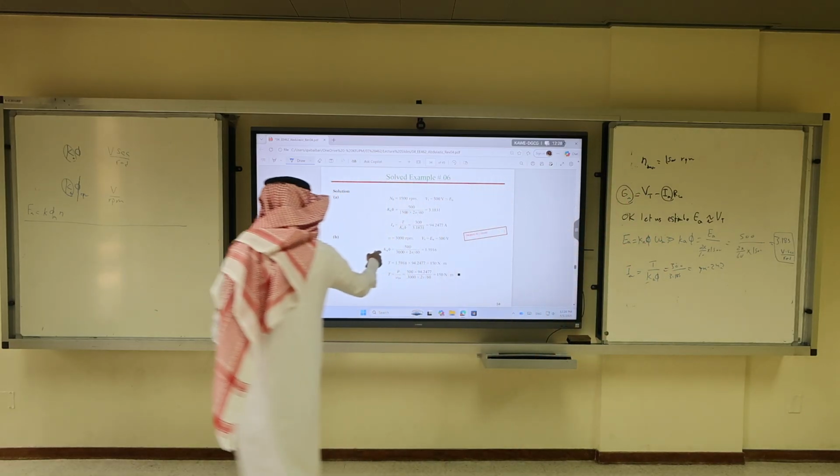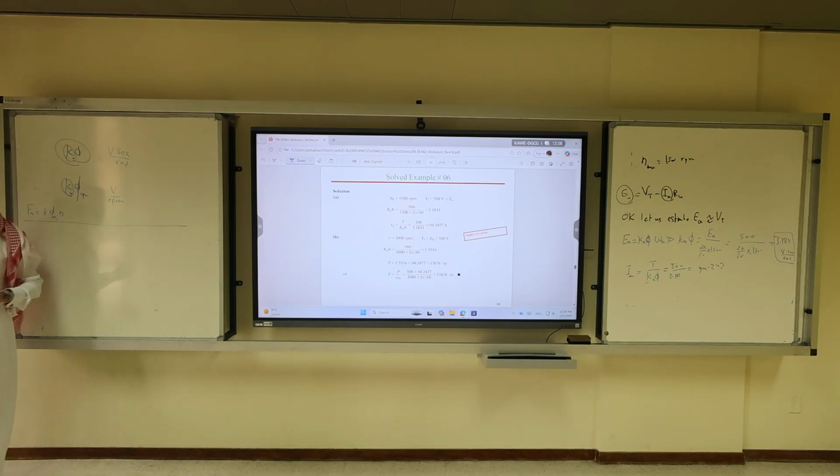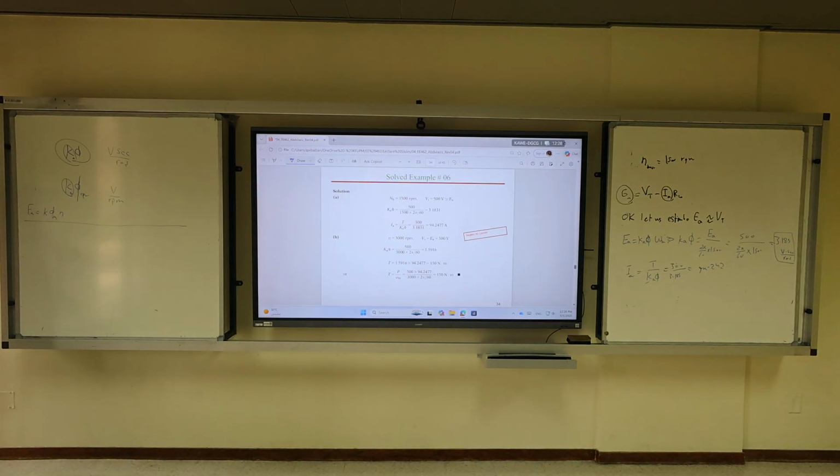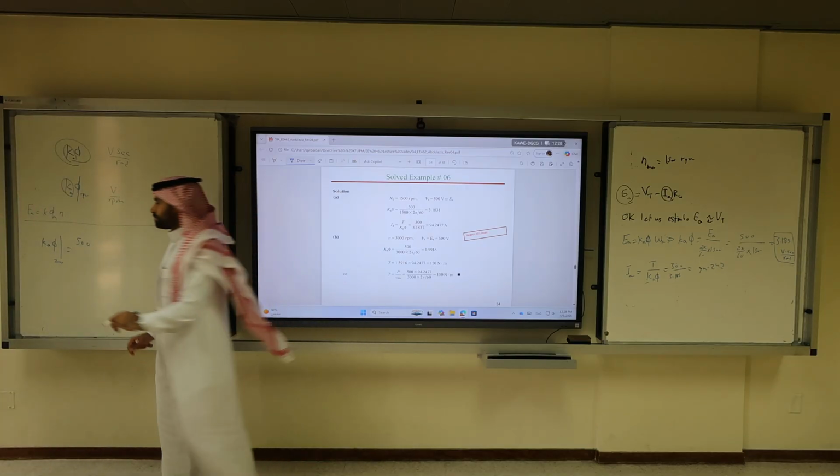So now let me ask you the question: will the constant stay the same now? Will Ka times flux be the same or different? It will be different. So we repeat the same method. Ka times the flux at a new speed of 3000 RPM is what? 500 over 3000.